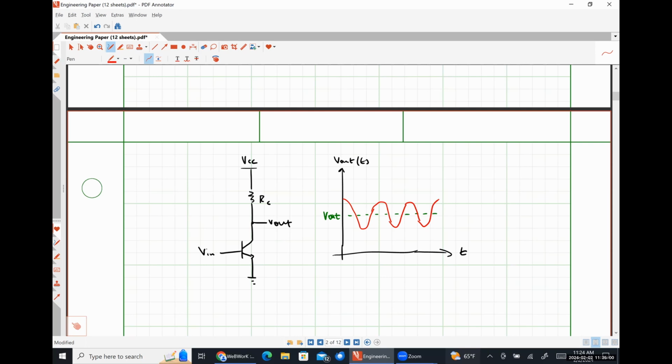However, let's say that this point right here represents where V out is equal to VBE. So with our current choice of where the DC part of V out is, which was established by our 4-resistor biasing network, we can see that under this particular condition, we're actually dipping into the saturation region on the negative half cycles of our output voltage, which means we're actually going to have a distorted output signal. Instead of going that deep, it would actually look a little bit more shallow, right?